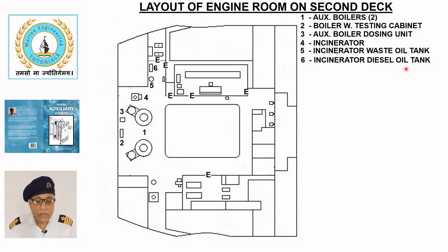Incinerator diesel oil tank. The incinerator diesel oil tank 6 supplies diesel oil to the pilot burner for starting the fire in the incinerator. In some cases, the pilot or diesel burner also helps sustain the flame of the main burner.